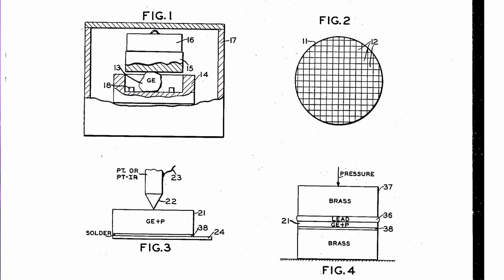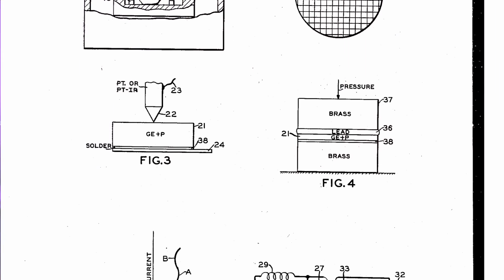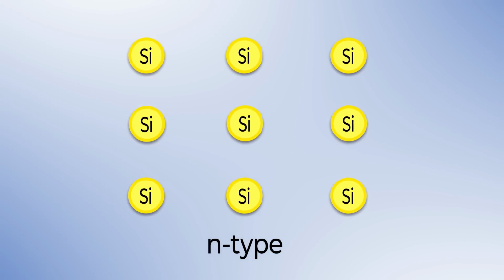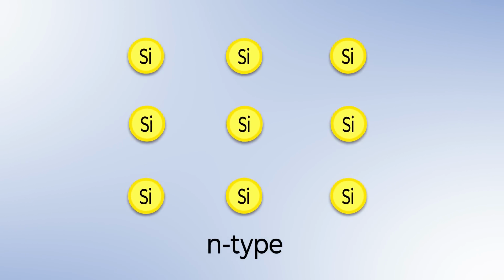The conductivity of a semiconductor is not predictable or exploitable in a way that is useful to electronics engineering. To make a semiconductor more useful, one must change the electrical properties of the semiconductor to make it more useful for electronics engineering. In the early 1940s, the patent was released for the ability to turn a semiconductor into a more useful material, referred to as doping. To dope the silicon and make it more useful, the silicon atoms were blasted with atoms that are either more negatively or more positively charged than the silicon.